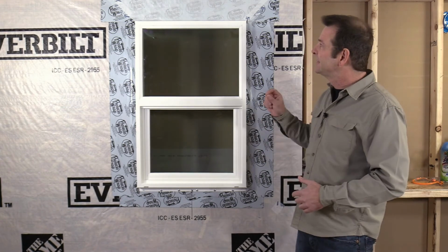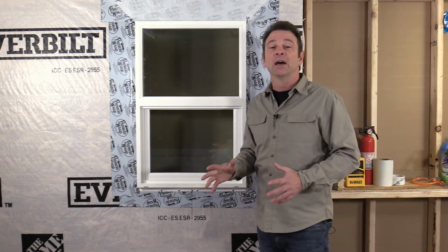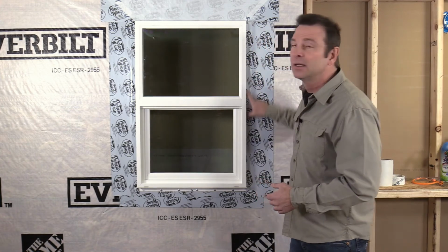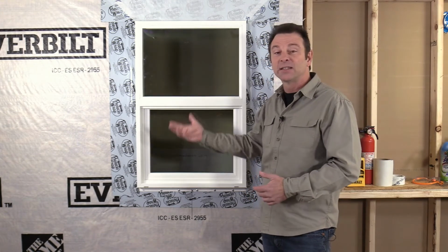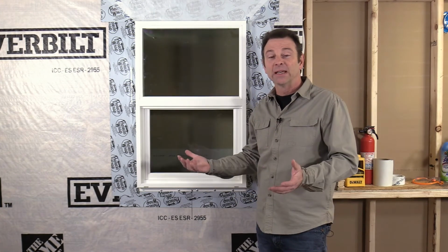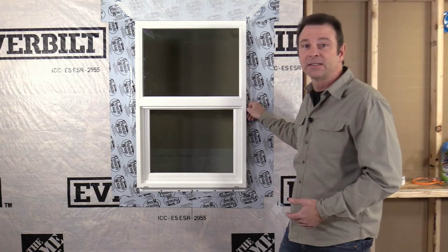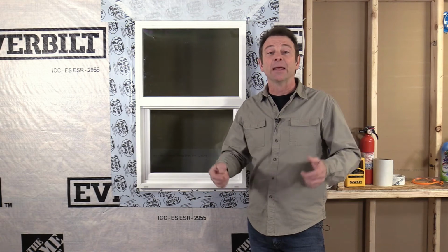So the only difference that you'll see, or a variation of this house wrap, would be how it wraps in on the sides. And we cut it right in the center of the sides of the rough opening. You might see that wrapped all the way in. I've actually seen the sides cut flush. This, or the attitudes about that specific cut, seem to be changing as we get into this idea of air leakage into the home. So make sure that all of them are done consistently and that they're done in a way that makes it watertight and airtight. And you can always check with the manufacturer's instructions to find out what they recommend.